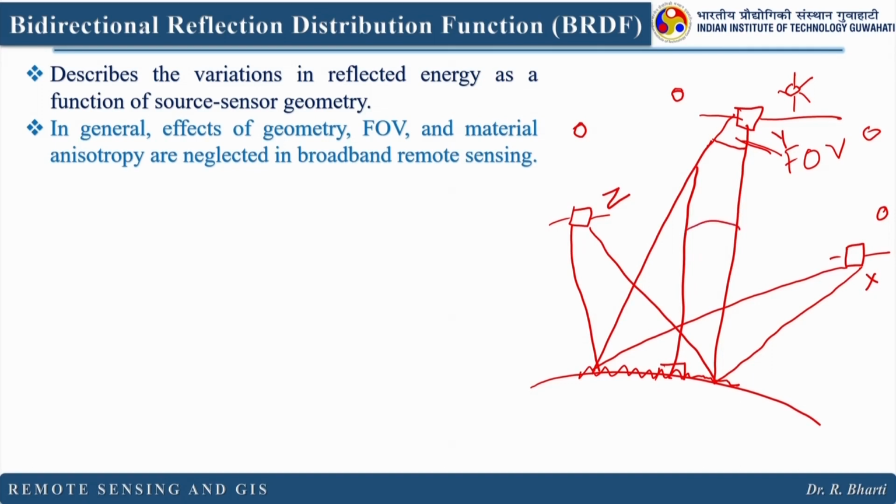It all depends on how well you have planned your research. If you want to compare such images or data sets, you have to make sure the time of measurement, look angle, field of view and pixel size are all the same. Then only your results will be meaningful.